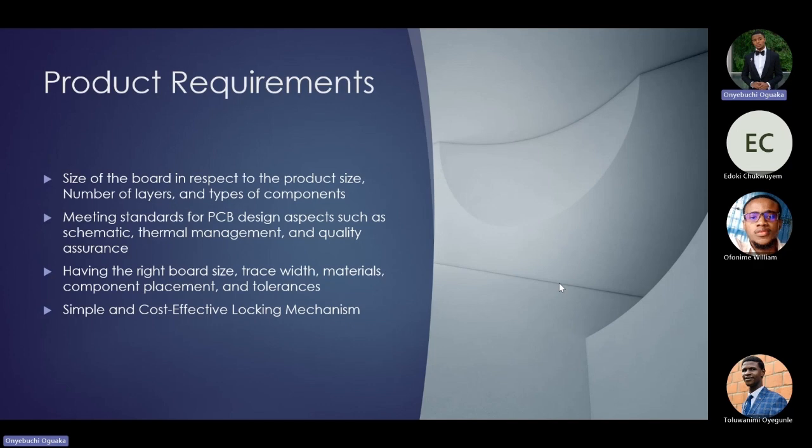Taking for example, the LM317 is a voltage regulator that is mainly used for limiting voltage, but there is another configuration that puts it into the phase where it limits current, and you can manipulate your way around that through calculations. There's a formula meant for that, and it's specified in the data sheet. But if you want to limit current using resistors, you said, did I answer your question?